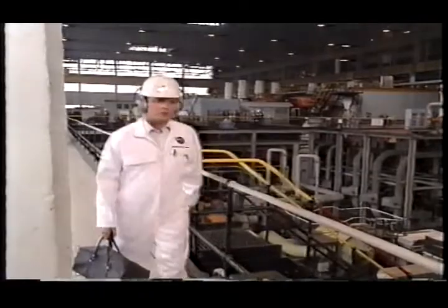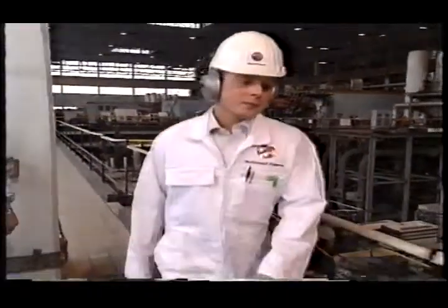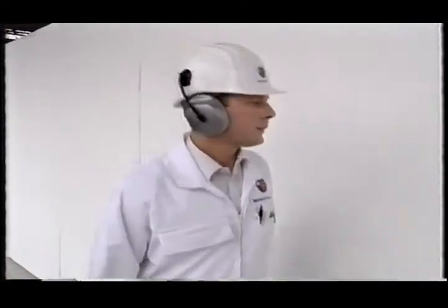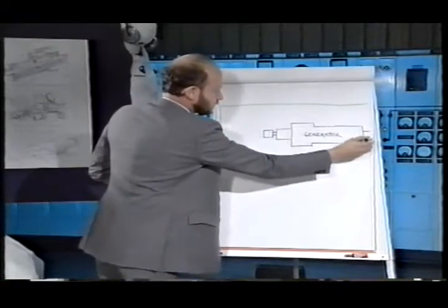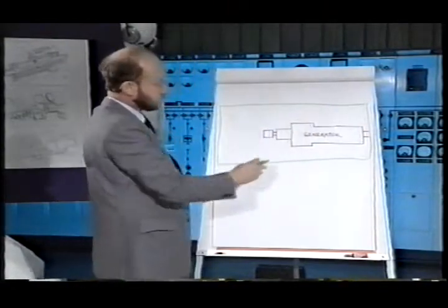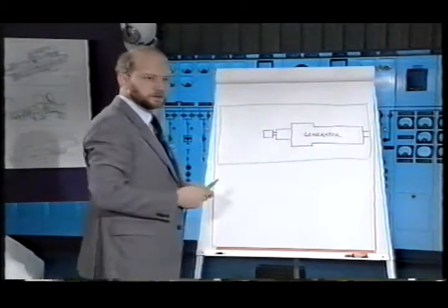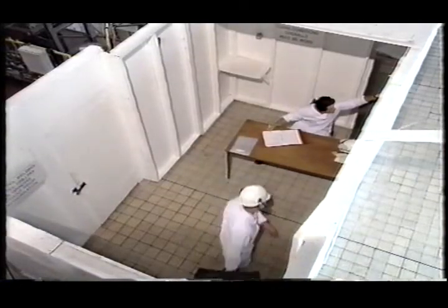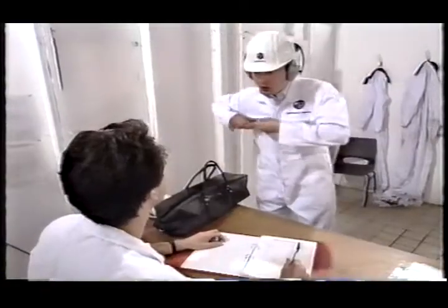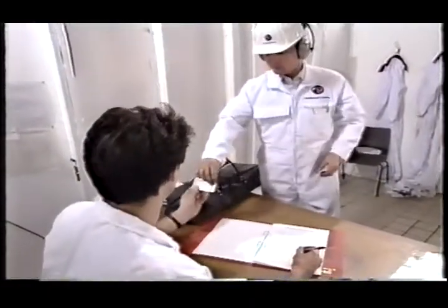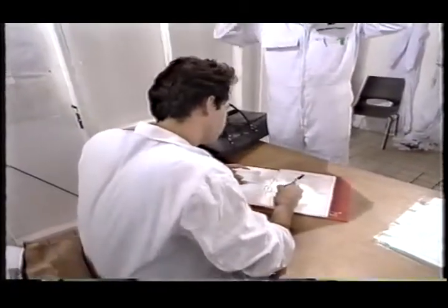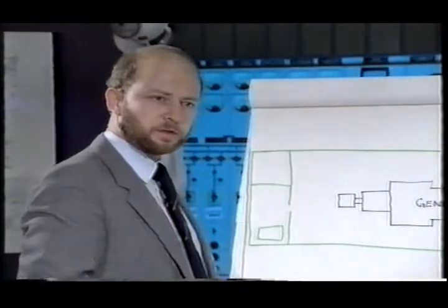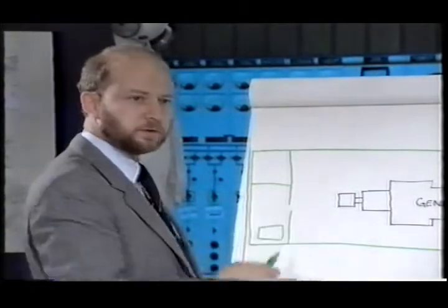Well, in the case of a major overhaul, in order to prevent unauthorised entry, the first thing you do is erect a barrier around the whole of the working area. And then you clean the floor inside the area and remove any unwanted equipment. Then we erect a control area with a guardian to record and monitor all entry and exit of men and materials from the area. We also provide an anteroom for the storage of the small tools and materials that are going to be required for the job, but they too must pass through the control of the guardian.